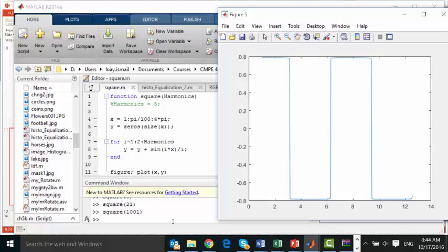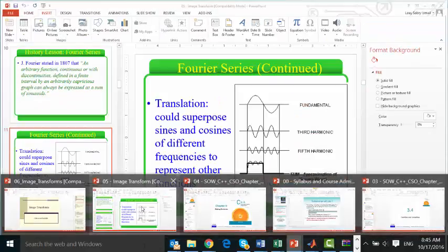This type of analysis is useful for us, so that, for example, after a certain level of harmonics, I can filter my signal. I can consider that, for example, for the 7th harmonic, it is fine with me. This is acceptable for me. So in this case, I can apply a low-pass filter in order to suppress all the frequencies above, let's say, the 7th harmonic. Like this, I will suppress most of the noise that can be added to the signal, because the noise actually has high frequency in this range. See what I mean? Is it clear?